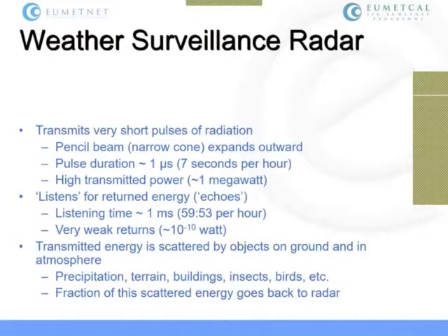The pulses are very short, at the level of microseconds. The transmitted power is very high, on the order of kilowatts or megawatts. It depends. After that, the radar listens for the return energy, so we can have those echoes that we can nicely see on our displays. As I said earlier, these returns are very weak, so they need to be amplified and processed until they are displayed.